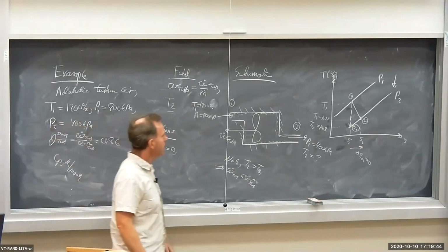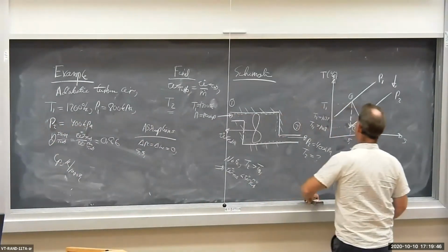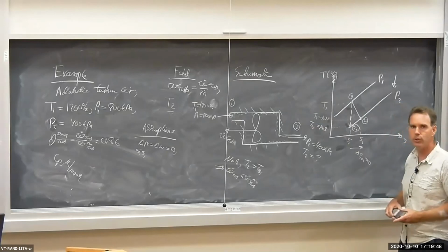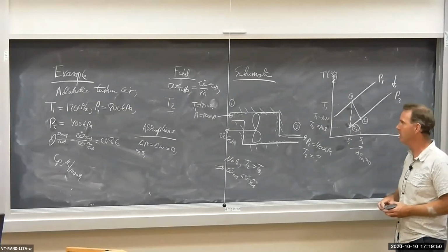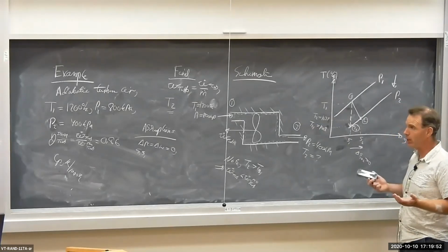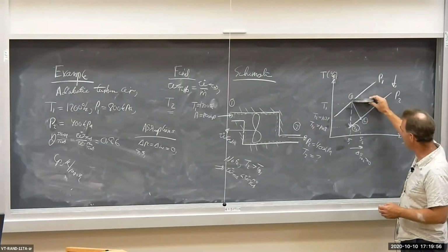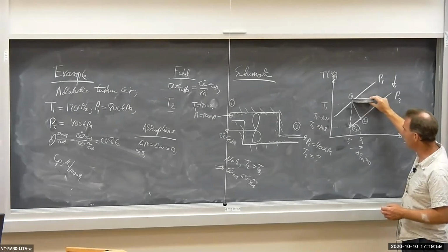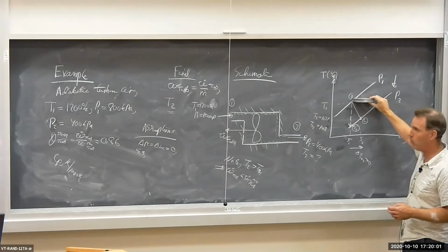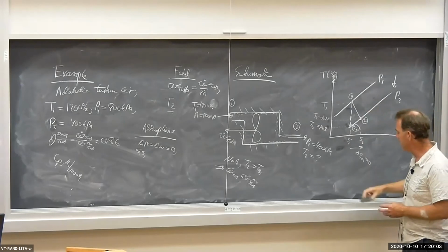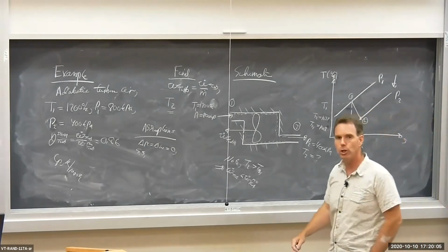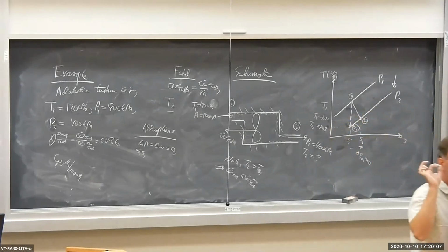In theory, I don't mean to get extreme here, but if the real device is so irreversible that its isentropic efficiency were 0, then in theory, the outlet temperature could be equal to the inlet temperature if it's not extracting any work. So an extreme case would be a turbine with an isentropic efficiency of 0.